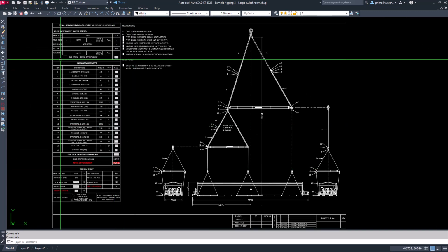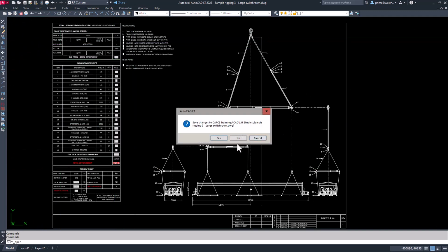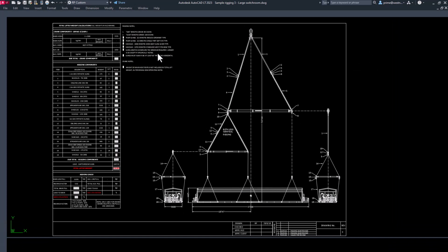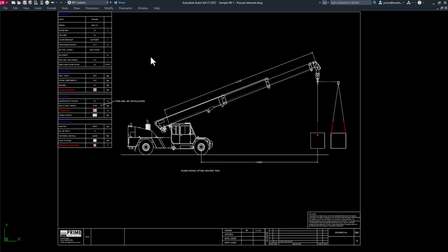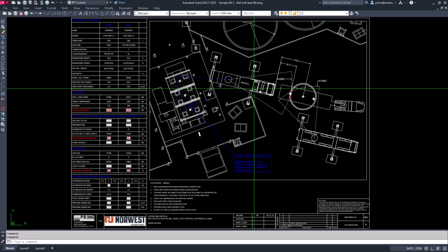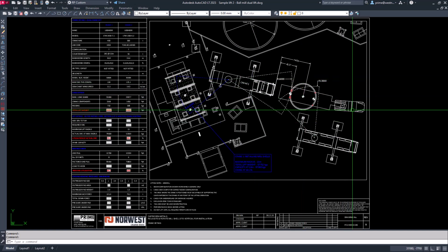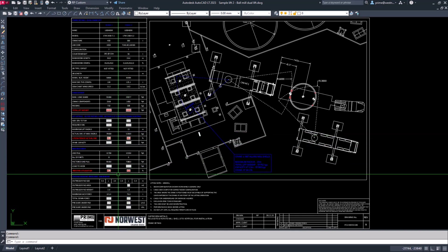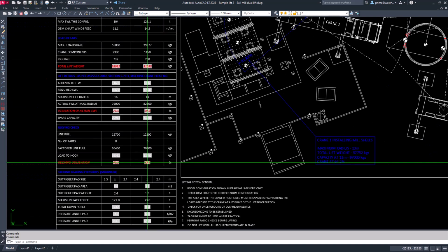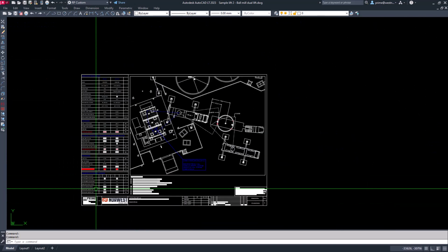Once we have that, we can move on to crane drawings, and again the drawings can be as simple as lifting a small piece of precast with a franna. Could be something quite a bit more complex, such as a dual lift at a ball mill. We identify where each crane sits, where the transport sits, where the load starts and where it finishes. We go into a lot of detail about crane configuration, about the load and the lift details. In this case we go through the dual lift requirements and required capacities. We check the reeving is sufficient and what the utilisations will be, and of course ground bearing pressures.